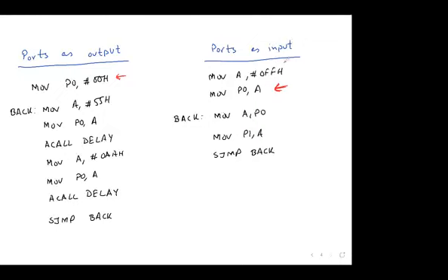Look at these things. In the second example, we moved this value via register A, but in the first example, we directly move the value. So you can use any of these instructions. Either you can use a register or you can directly use the value. That is totally up to you. Also over here, we have used register A, but you could have simply written move P1, P0. This is also a valid syntax. You can directly move from port to port. No problem with that. So is it clear up to this?